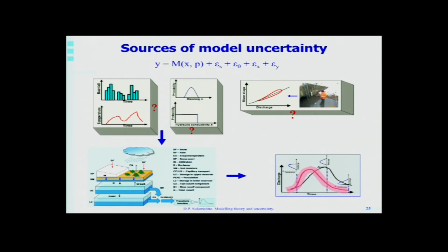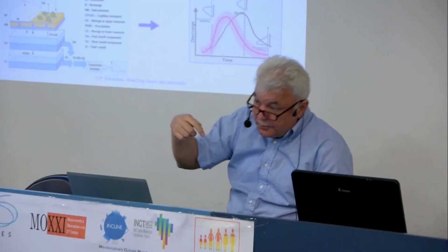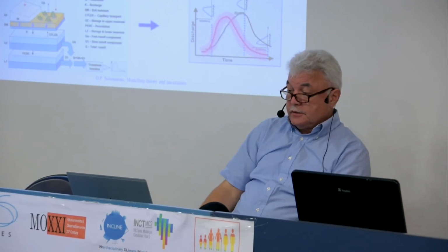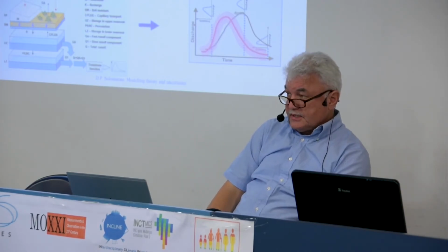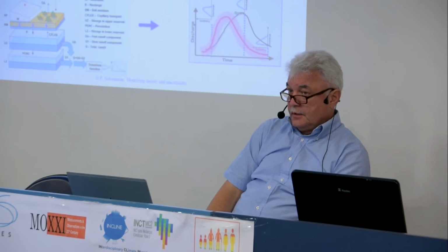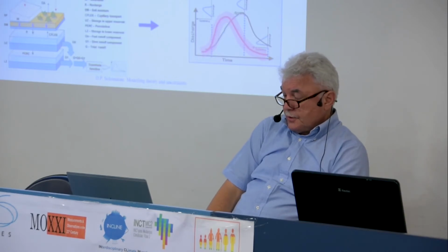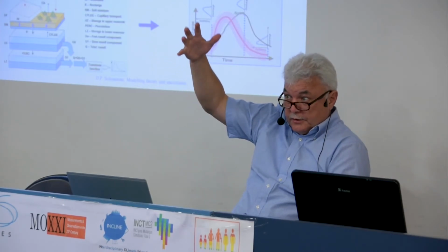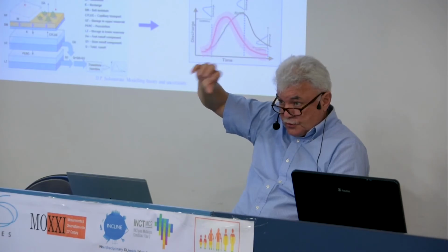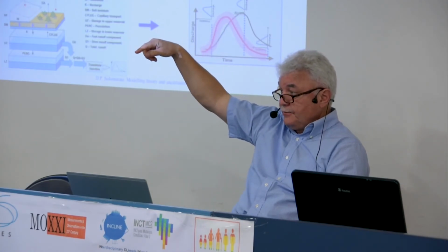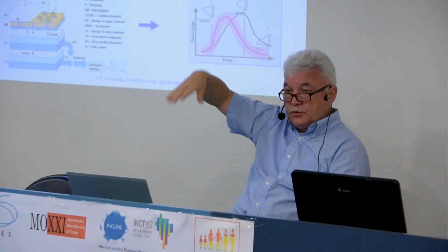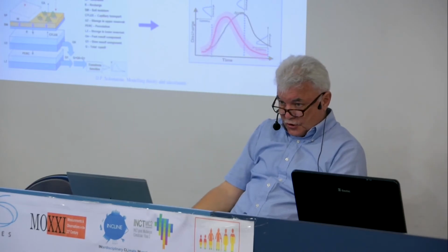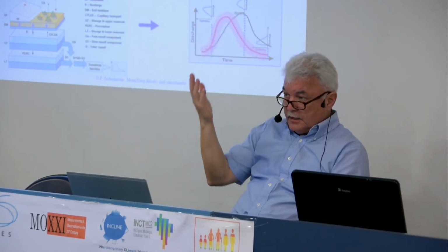That's right. But I think perhaps what you're also hinting at is that we could in principle sample the rating curve from certain distributions. So if we assume your rating curve is uncertain, let's assume some probability density function that is associated with the uncertain rating curve. The rating curve then would generate a number of discharges instead of one, many.